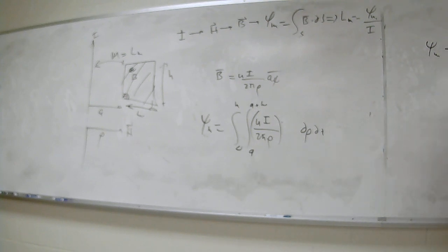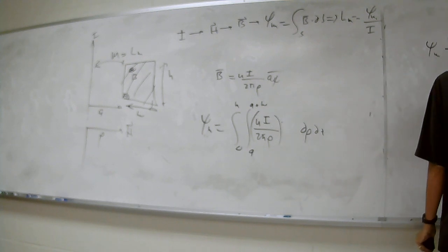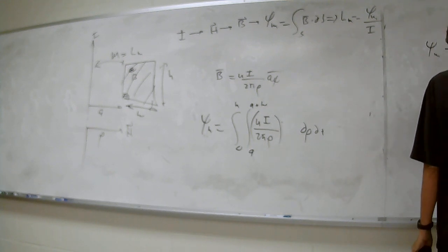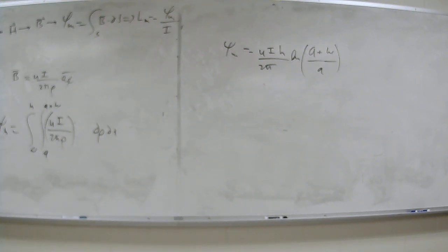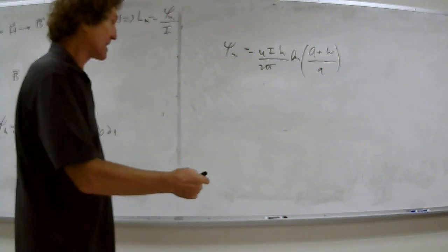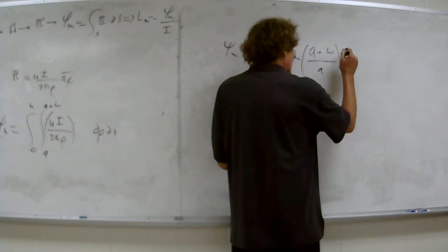And what about the height integral? dz gives h. And that's the magnetic flux that penetrates that loop per one turn. Next question, what if I have 2 turns? It's not a trick question. 2 turns, it would be twice. 3 turns, 3 times. N turns, N times. So normally you'll see an N come out here.